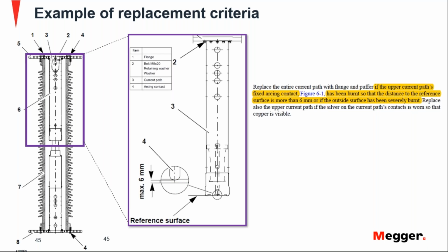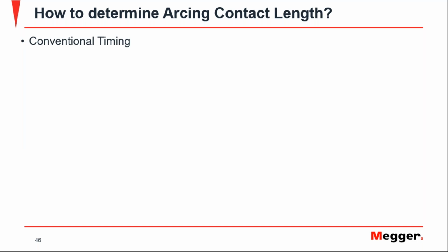Well, the easiest way is with a visual inspection, but visual inspection is not very good because that means a major maintenance on the breaker. And also CIGRE studies show that breakers fail mainly after major maintenance. So probably not the best thing to do, and if you do that, then you just replace it, because you're not going to assemble the breaker again without replacing it. So there's testing that can be done for that.